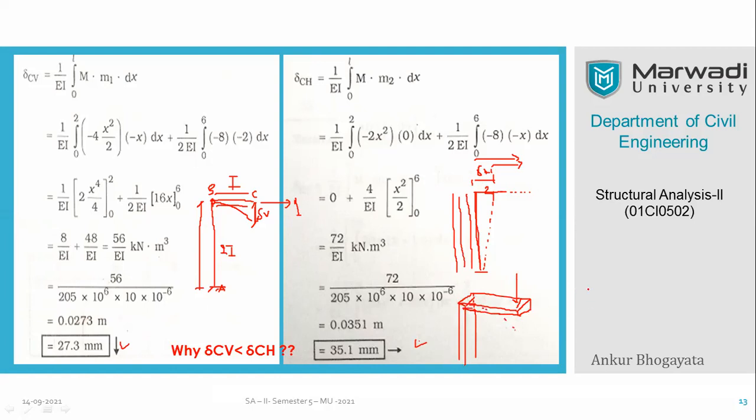And if I change this orientation from horizontal to vertical, like this, I'm using this area just to demonstrate, you can again very well see where it will impact. It will impact the moment of inertia itself, because now you have tremendous depth of this section. So orientation we generally avoid at this moment. That's why we take I as constant for both cases.